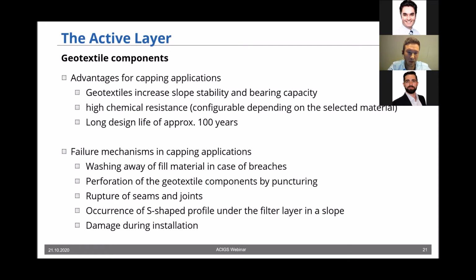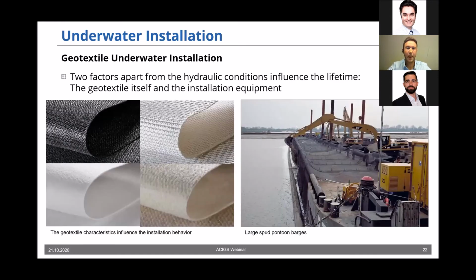You might have occurrence of S-shaped profile under the filter layer and a slope, and you can have damages during the installation process. And therefore, of course, choosing the right geotextile is very important, but also it is very important to choose the correct installation equipment here. You can see this picture shows different geotextiles, and I think you can just imagine that some of them have a higher tensile strength than other ones.